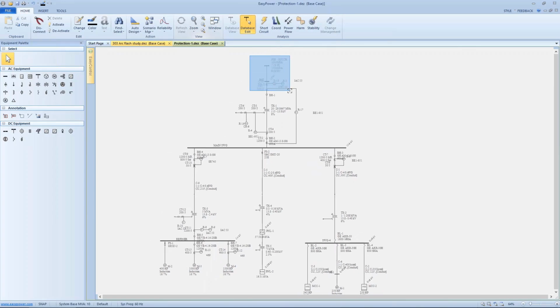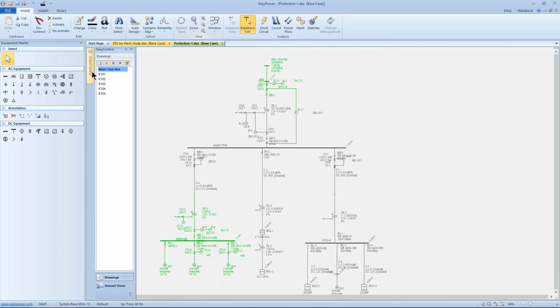And so the tool allows me to pick up, let's say, the utility. Let's say I'm adding a motor, or I'm exercising a motor, or trying to decide either power factor correction, or the effects of a VFD drive. And so I might select, let's say, the utility and the bus that I'm considering making changes on, and I'm going to create a new drawing.